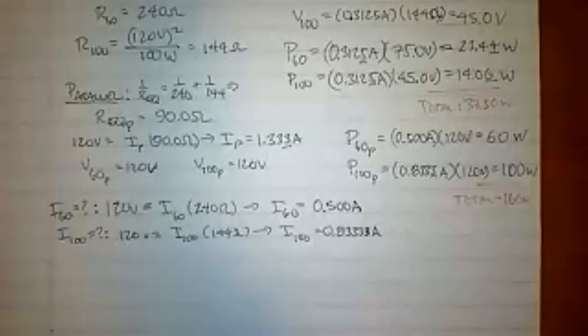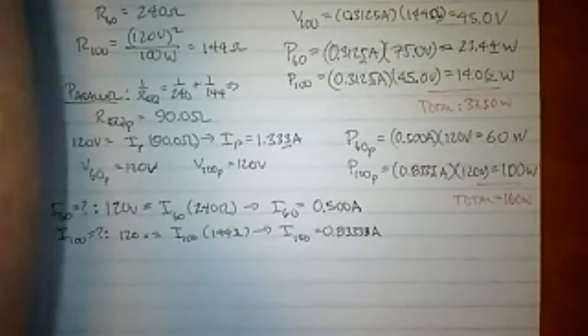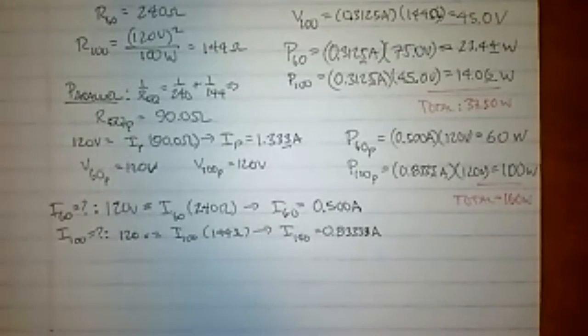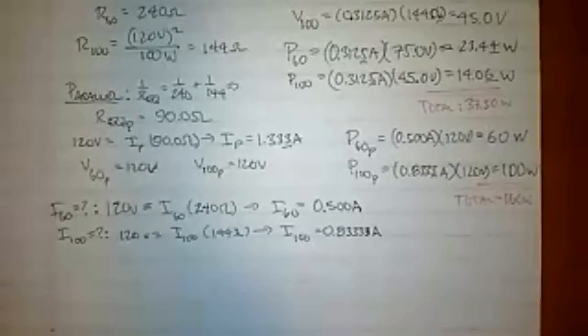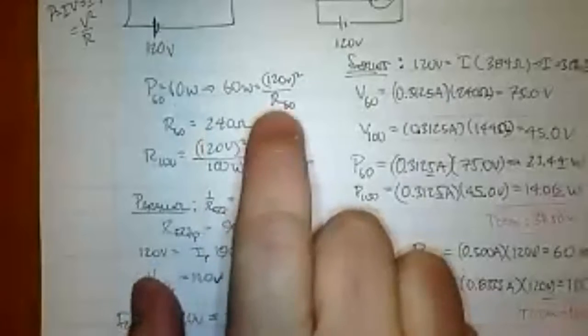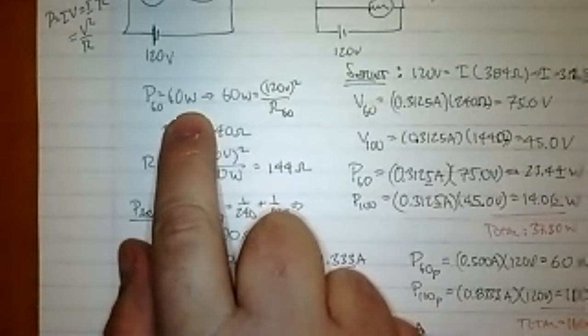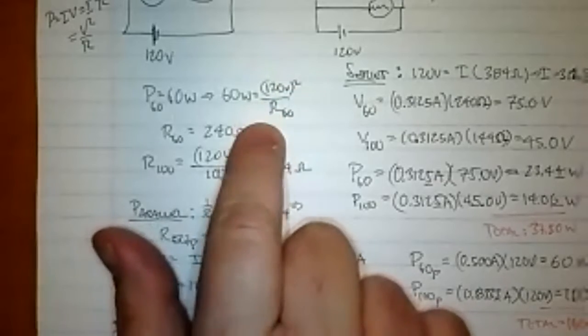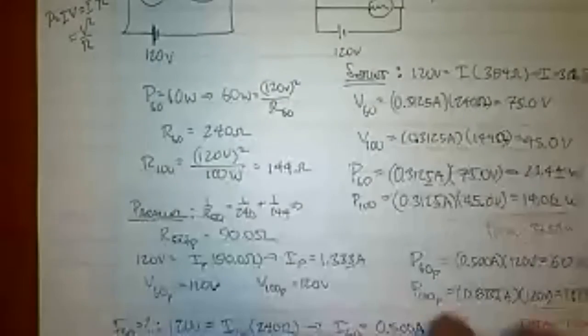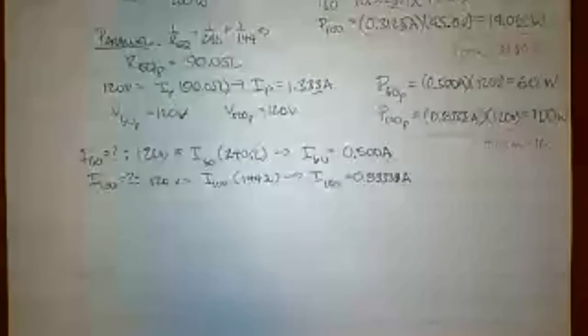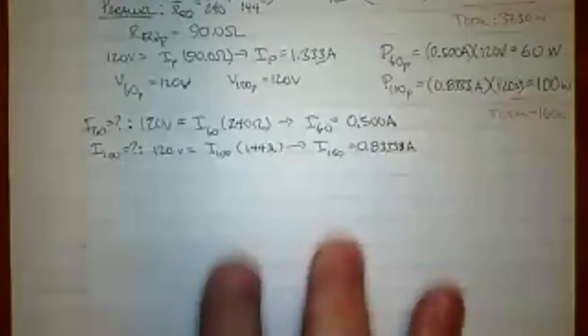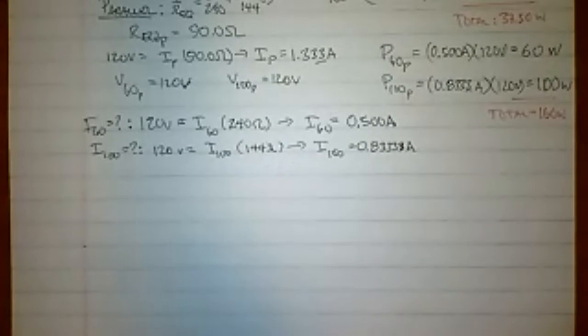I noticed that the power dissipated in the parallel circuit matches the advertised values. Is that a consistent pattern? Yes, that's exactly how we connect them. And even that came down to this calculation, because when they say a 60-watt light bulb is really meant for 120 volts, you'll consistently get the resistance so that it will give you exactly that wattage. Whenever that's the way things are wired in a house, it's basically in parallel. That's why they work out that way. That's wild. It's kind of neat, isn't it?